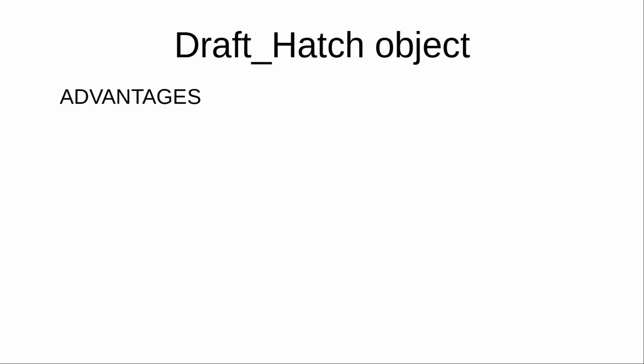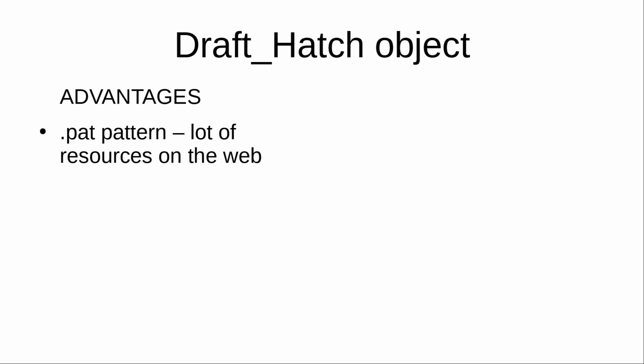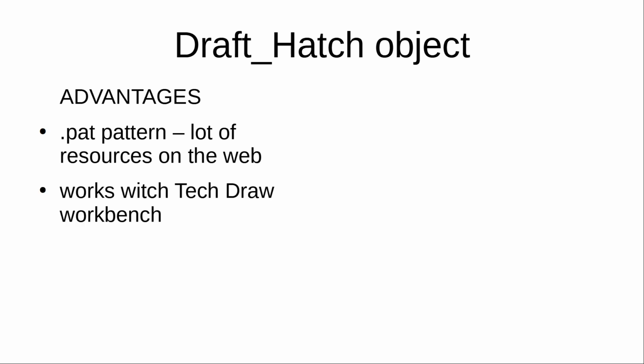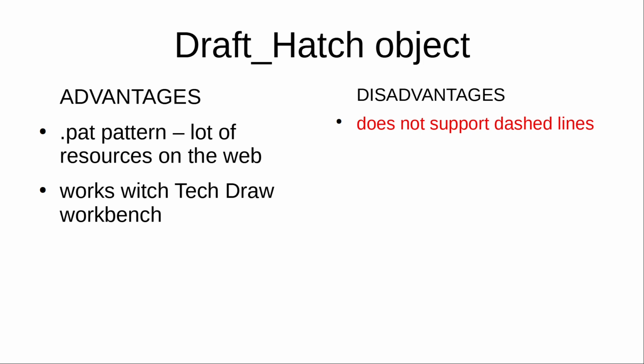Now let's take a look at advantages. The advantages, it uses .pat patterns, which there are a lot of resources on the web. And the most important thing is it works with TechDraw Workbench. The disadvantages are it does not support dashed line. That's quite a big one, but we have to live with that as of FreeCAD 1.0.